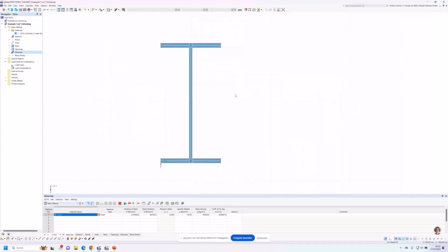The cross-section should be a rolled T profile to which a lower flange is welded. The round radius is 15 millimeters. I can define lines to create them or use the create round corner function. In this case, I create the round radius using the function, and you find this function here in the bottom.